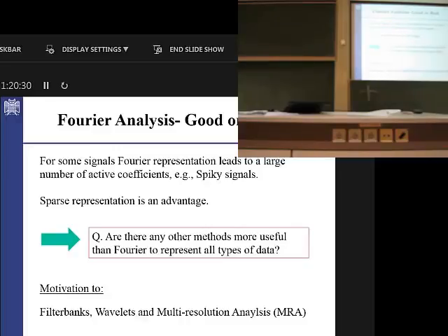So one slice of the spectrum of the signal. Whenever dealing with the frequency components is important, you're dealing with the frequency, you use filter banks. When frequency by itself is not important, just the approximation and details are important, then you will go through the wavelets.